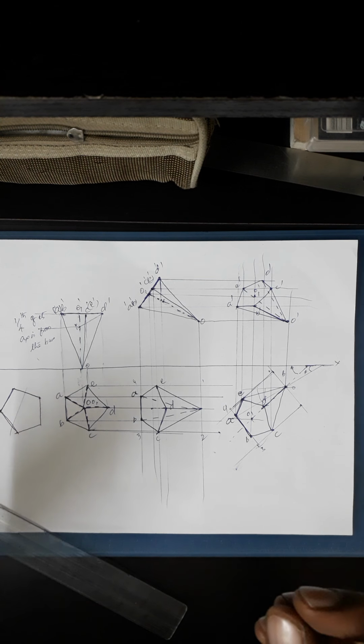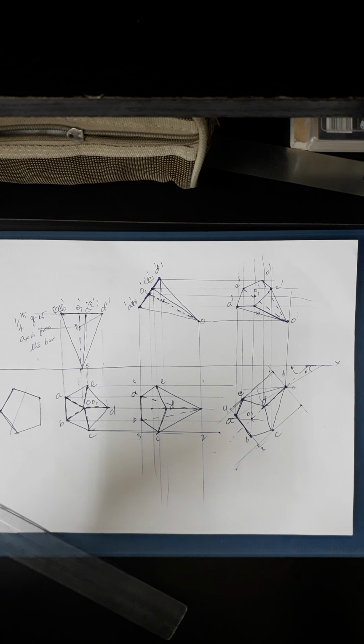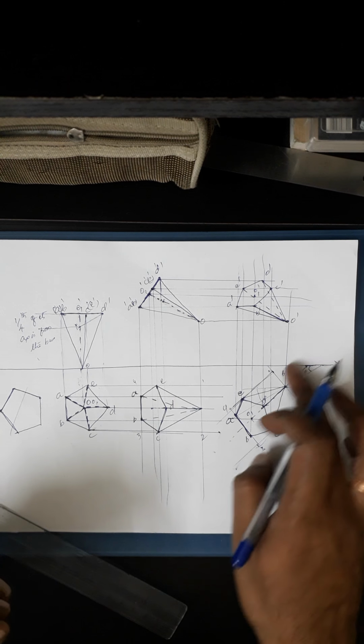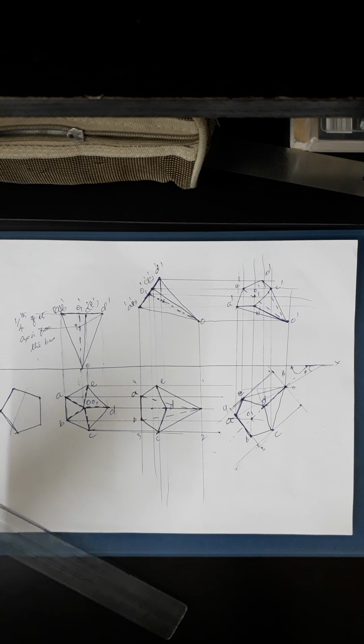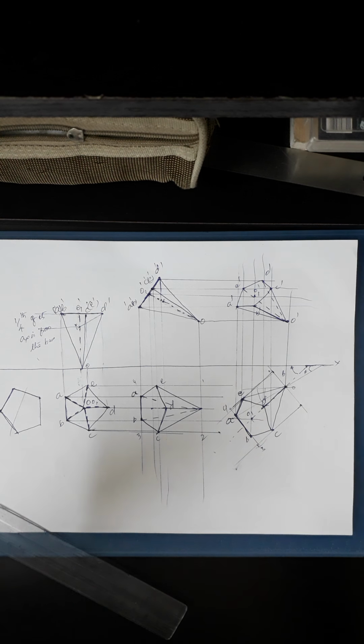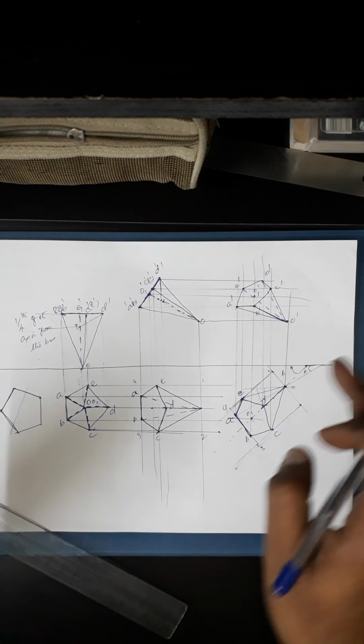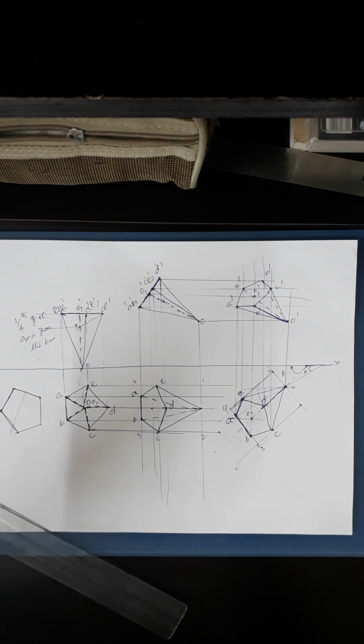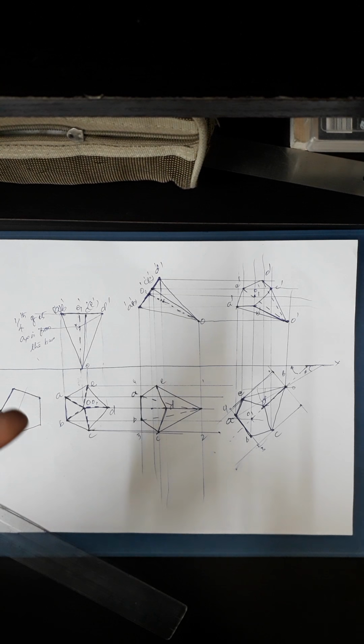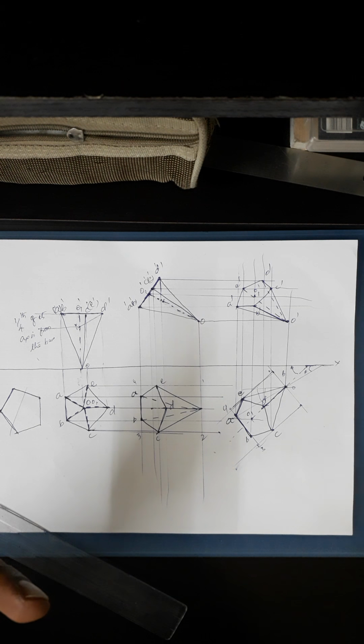So since they say freely suspended and axis is inclined at 30 degrees to VP, then you have to go for taking beta. If they say instead of freely suspended that the axis appears to be inclined, then you need not go for taking beta directly at that given angle. You can draw then appears to be inclined, then top view of the axis is inclined with VP. They say sometimes the top view, for the top view the other word, projection of the axis on HP is nothing but the top view only, that will be given.